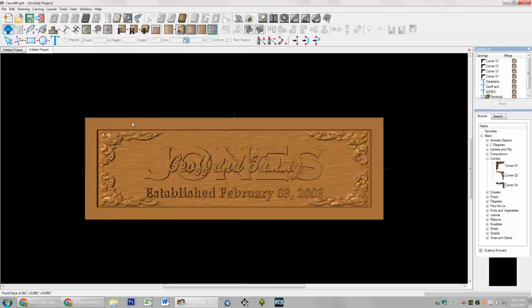I also do have a jig I carve these in. It's basically just 2 1-inch rails that are adjustable as far as how long they are, with a 3.5-inch extension on either end.